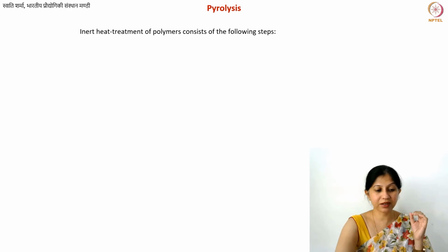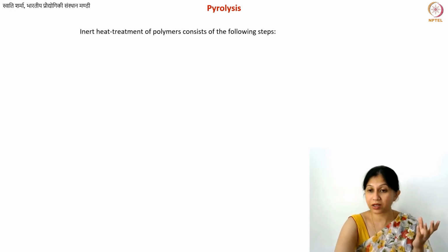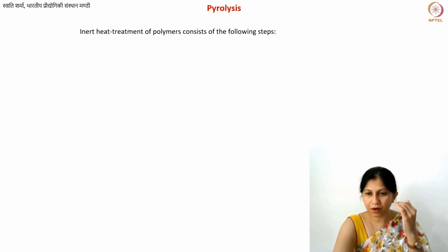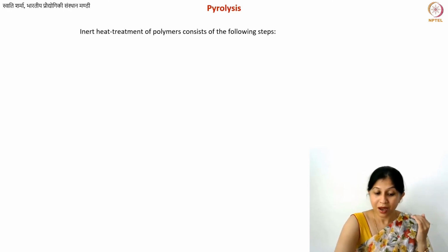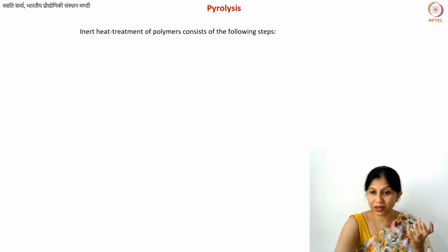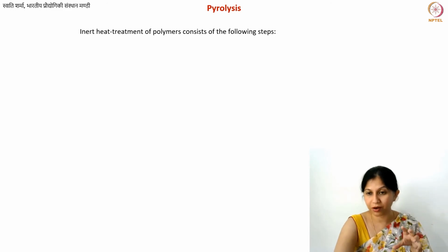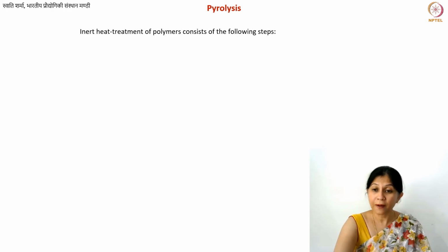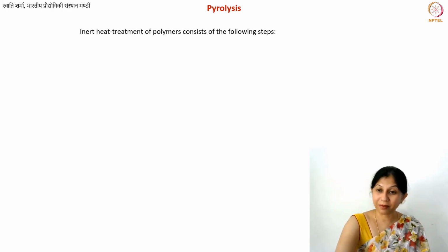Because there is a certain strength, for example, of a carbon-oxygen bond. Now, depending upon your polymer, you may go a little bit above or a little bit below the temperature, but depending upon the energy of your bond, it will not differ too much, because that is the energy of the carbon-oxygen bond or carbon-hydrogen bond, in the case of aromatic structure, ring-like structure, or aliphatic structure. You may sometimes also have some catalytic elements inside.